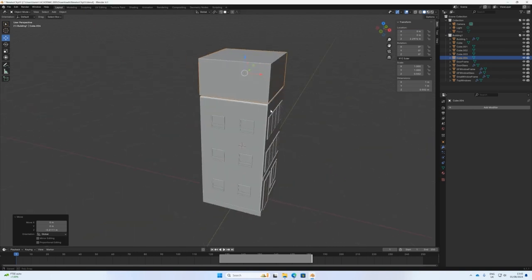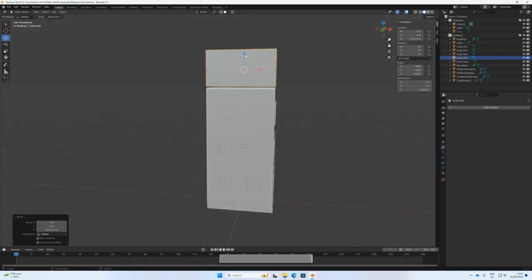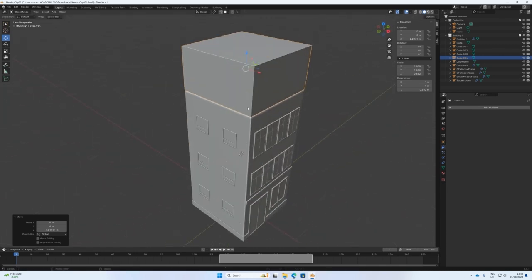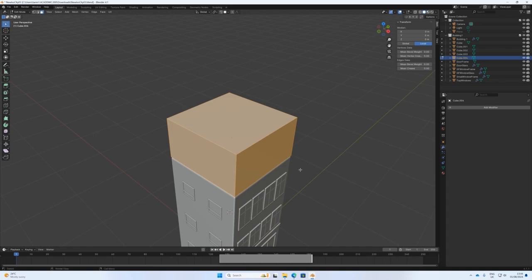My reference. So now I don't have a triangle object, but I can do it with the cube. So I want to use this cube, and I'm going to change it to give it that kind of roof shape. For that, I'm going to go to my edit mode. Right here, you have the object mode. This is your object, and then you want to make modifications to this object. So you go to the edit mode, as you can see.